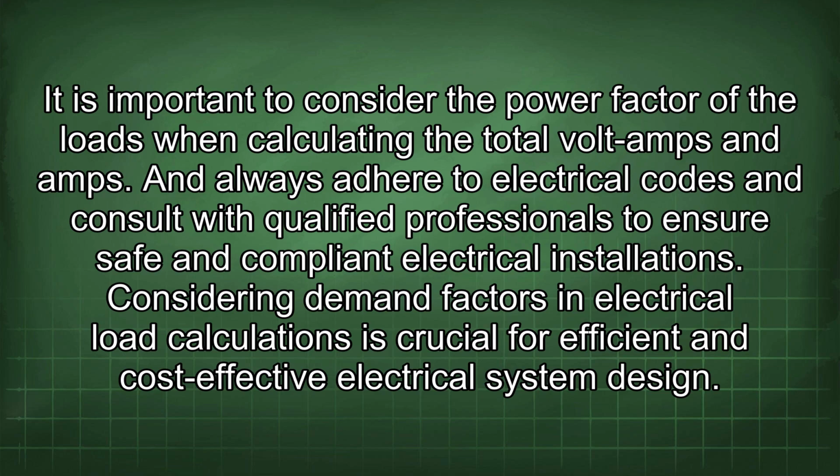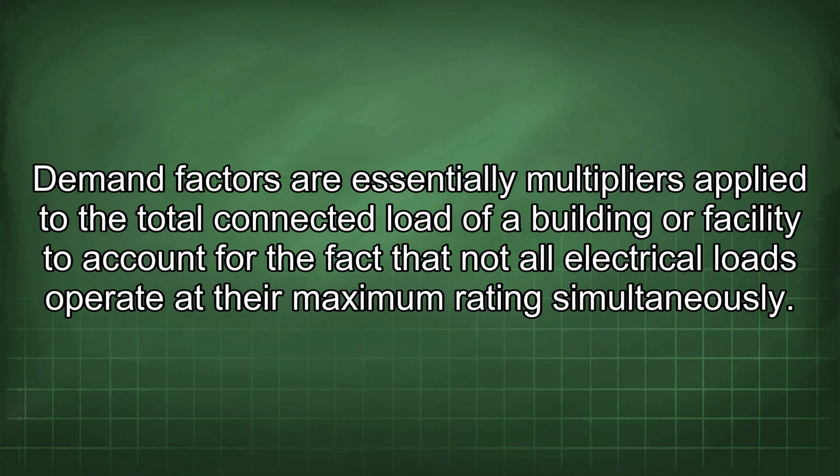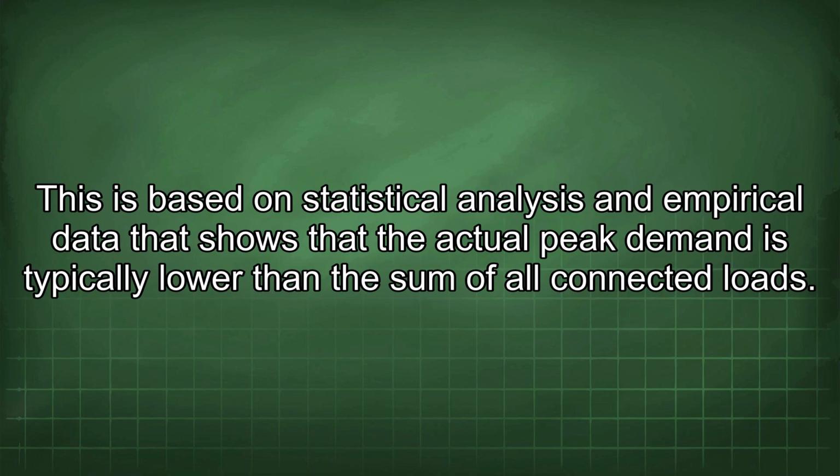Considering demand factors in electrical load calculations is crucial for efficient and cost-effective electrical system design. Demand factors are essentially multipliers applied to the total connected load of a building or facility to account for the fact that not all electrical loads operate at their maximum rating simultaneously. This is based on statistical analysis and empirical data that shows that the actual peak demand is typically lower than the sum of all connected loads.